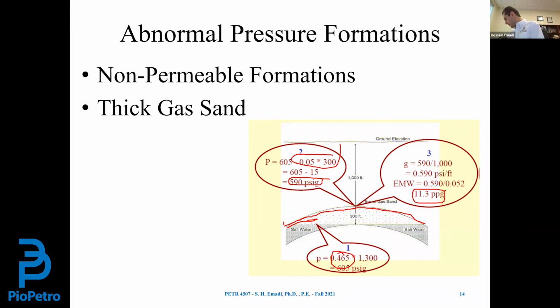they plotted the rate of penetration versus the amount of overbalance, because the more overbalance we have, the more difficult it becomes for cuttings to get detached from the formation. So the longer it takes the cuttings to get detached, the slower the rate of penetration we get.